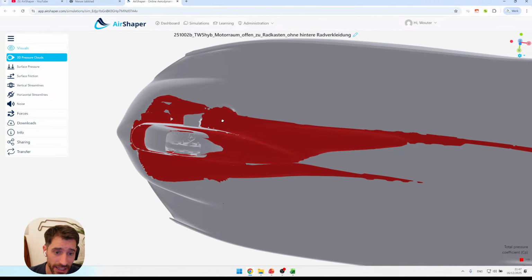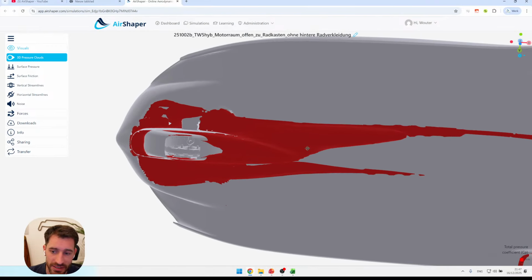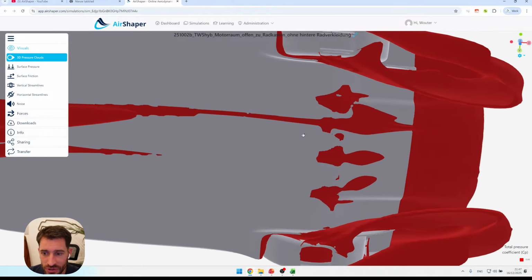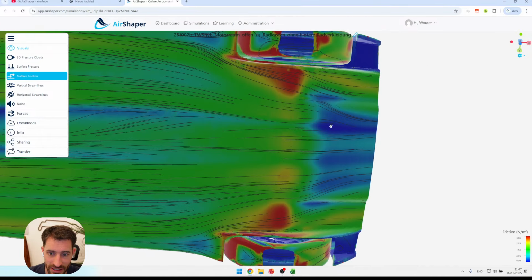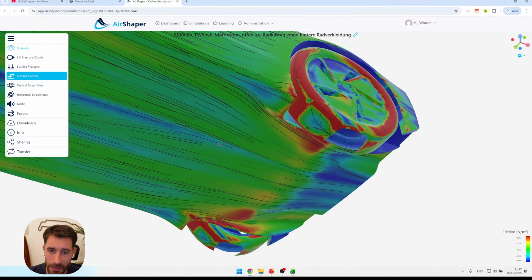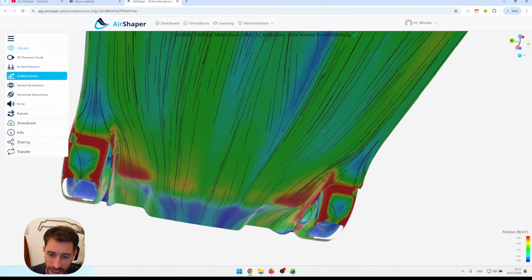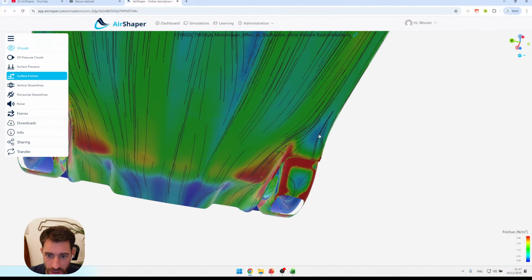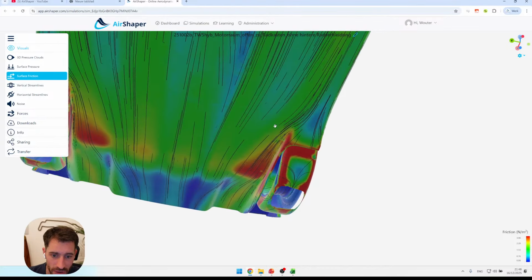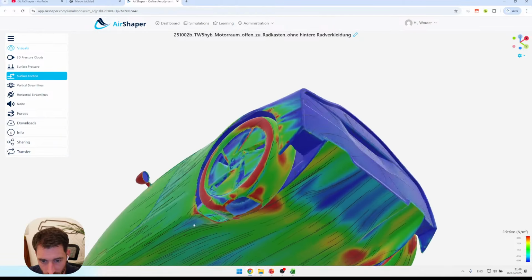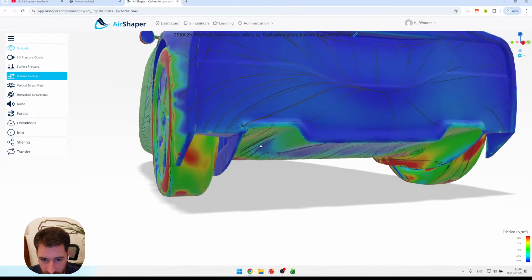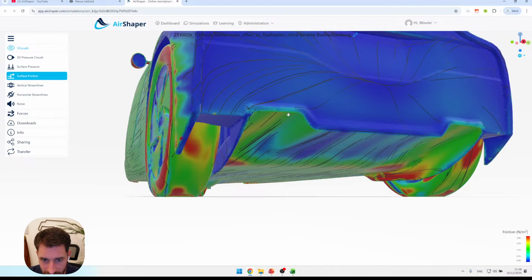It's still an asymmetric airflow because the suspension is only coming from this side. The airflow traveling downstream is actually flirting with flow separation, but it's not separated airflow. It's slowing down, but it's not stalling. Then you have this very organic combination of the rear wheel deflector combined organically with the sidewall to keep the tire wake under control, combined with the most aggressive part of the diffuser, which here featured this S shape going upward into the diffuser. So here you can see the diffuser going up and then flattening out again.